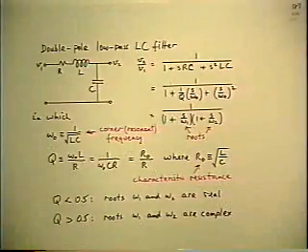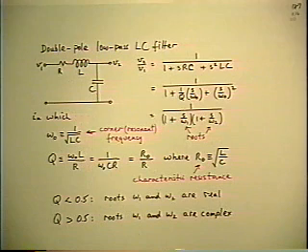So all of this is by way of hopefully persuading you that understanding what goes on with a basic RLC network is still important. Even though, as signal processing designers, you may want to simulate an inductance by using a couple of op amps and some integrated R's and C's, but still you have to remember that what you are simulating is L di by dt, and you are not simulating 1/2 Li squared, the energy content of the inductor.